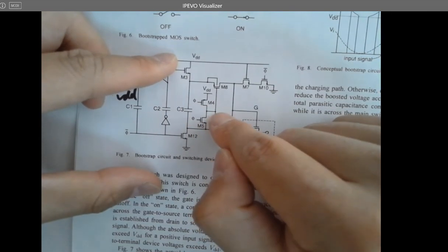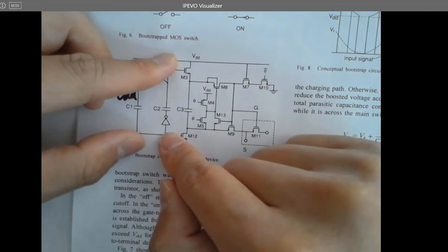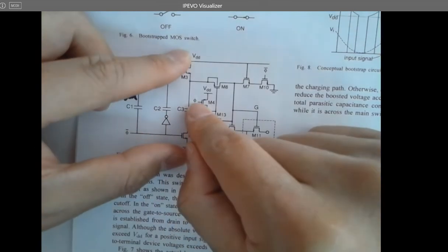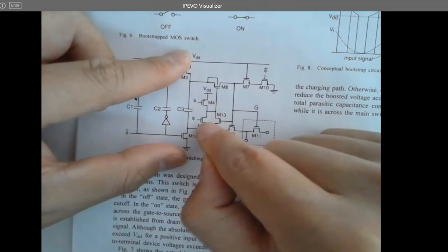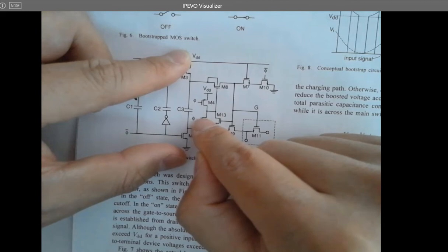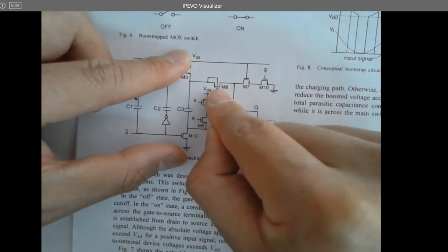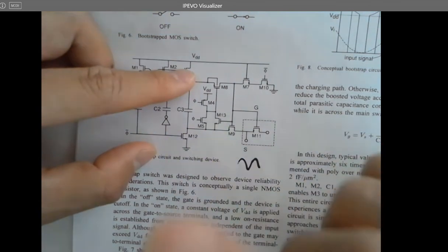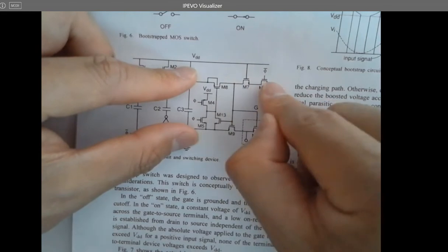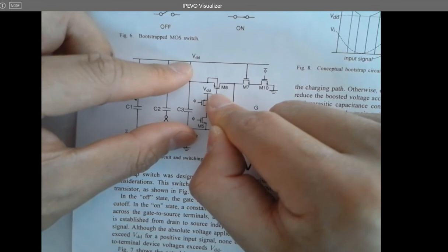And what is this point? So whenever this is high, phi bar is high, phi should be low, right? So phi is low. For this inverter, that's a PMOS, that's an NMOS. For this inverter, phi is low, which means the PMOS is on, NMOS is off. So this is off, this is on. So VDD will be passed to this point. So whenever I'm charging up, it's still the same cycle, right? I'm charging up C3, and also I'm resetting this point. At the same time, I'm giving a VDD to the gate of this PMOS. And what's happening? If you give a high voltage to the gate of the PMOS, what's happening for the PMOS?